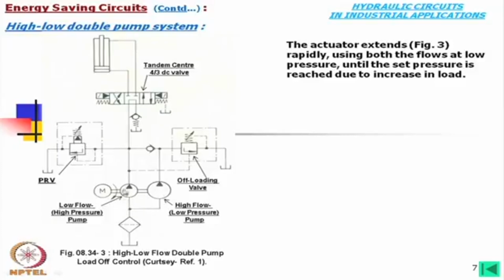So, full power is being utilized, the 10 megapascal into flow of this. Now, how is it operating? Let us study this one. Essentially in this circuit, there is one reservoir, the strainer, and then the common input, and here is a common shaft driven by this motor. So, when this motor is rotating, both pumps are rotating.